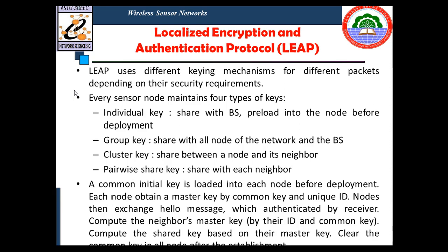For this, the initiator sensor node has to find where the destination is. It has to do location discovery. During aggregation of sensor data, the location information of the sensors must be considered. Each node couples its location information with the data in the message it sends. GPS is not always usable because it cannot reach nodes in dense or indoor areas, and it consumes high power. So we need a low power, inexpensive and reasonably accurate mechanism. For this we need to localize the sensor networks.